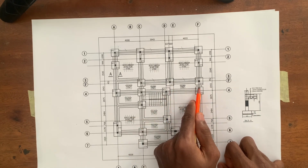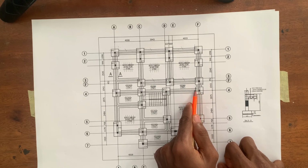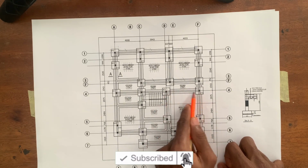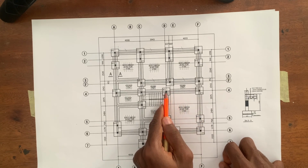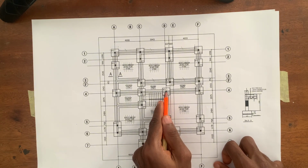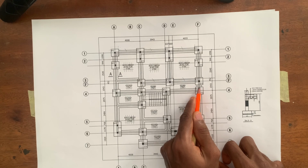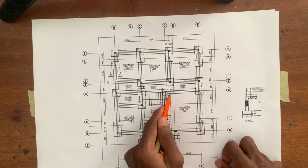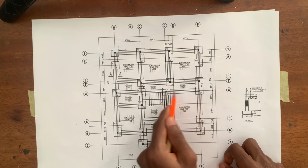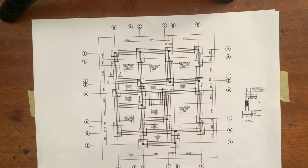So we now need to determine half of the two of them. When we determine half, we can now minus it from the center to center dimension from the column points, which we just calculated as 5230. So half of 1200 for base type 1 is 600. Half of that of base type 2 is 600. So we're going to be minusing 600 on both sides from 5230.